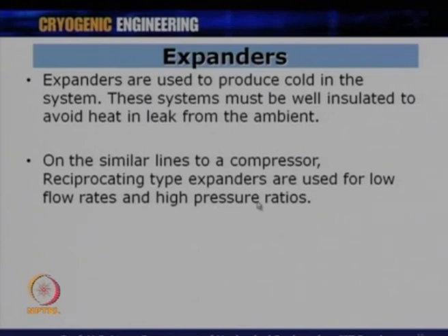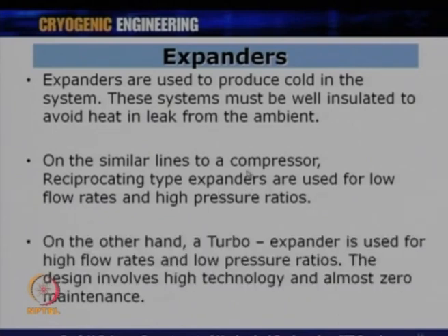If you want to expand the gas for a high pressure ratio, then one should go for a reciprocating expander, but then it can take a limited flow rate in this case. On the other hand, a turbo expander or a rotary expander is used for high flow rates and low pressure ratios. The design involves high technology and almost zero maintenance.